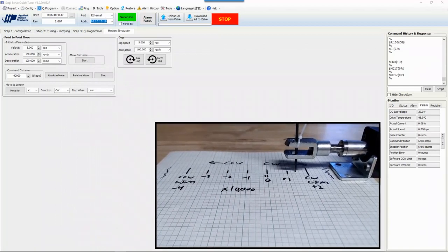So we can see our motor, our actuator rather, is sitting with the screwdriver sort of pointed in between some numbers. So let's jog it. Let's go 1 RPS, and let's go counterclockwise. Oh, there we can see it move. And clockwise, there we go. Okay, so let's try to land somewhere about on the, let's actually go for the home mark.